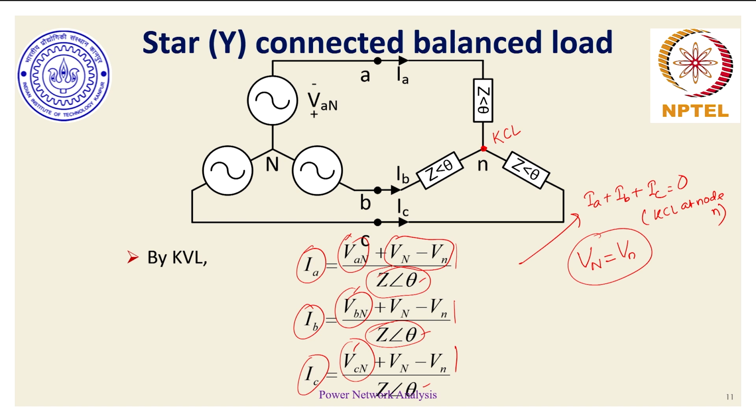So with this, we come to our second advantage: since the neutral points under balanced operation are equal, even if there was a physical wire connecting these two neutral points, since this wire does not have any potential difference across it, no matter whether this wire was present or not, the potential difference never exists. As a result, the current through this wire will not exist. It will always be zero. That's where the advantage of saving the return conductor is applicable for three-phase circuits.